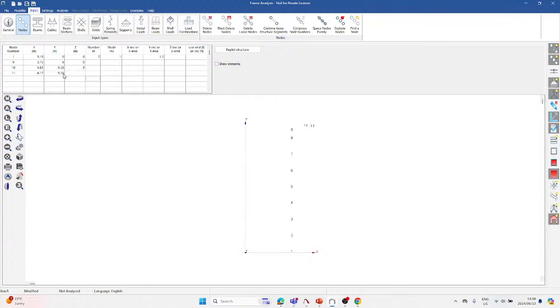And then for the z dimension, it will be 0. If you leave the z direction open, the program will automatically assume that it is 0. And then I want 5 extra purlins. Node increment should be 1, and then the spacing between the purlins is 1.561, and then they should be